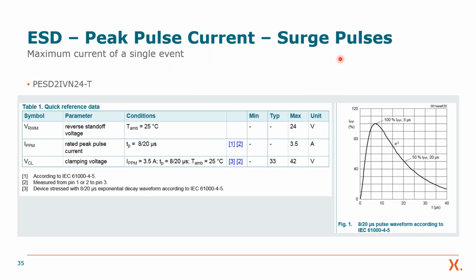So this is the clamping voltage, but when you look at a data sheet, you have to be a bit careful, because there are usually several clamping voltages stated. And unfortunately, always the same name is used. So one clamping voltage is you shoot at the device under test, and you record the waveform to get an understanding of what the IC would see during an ESD event.